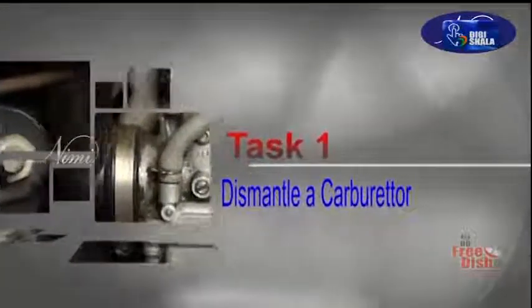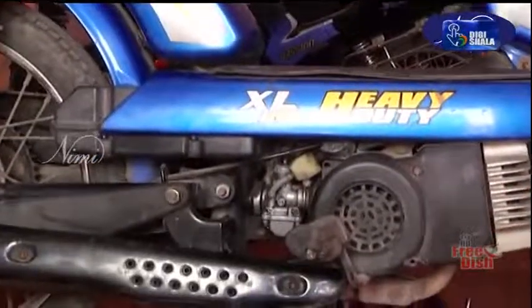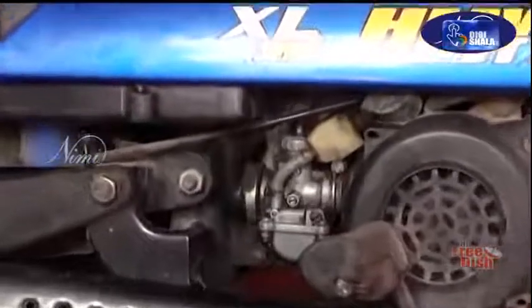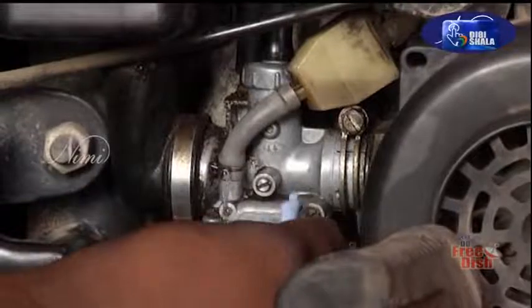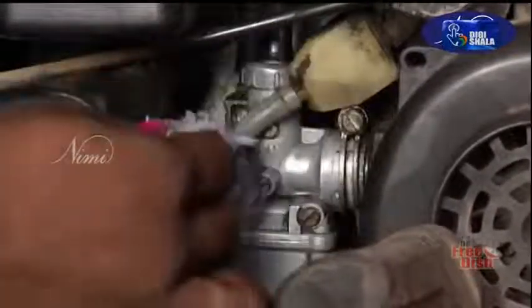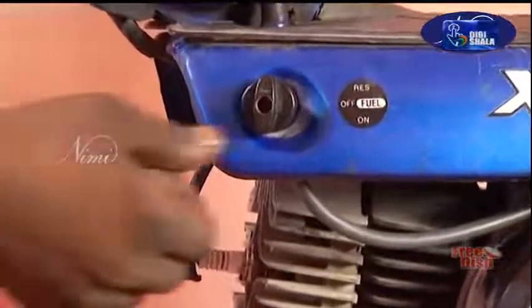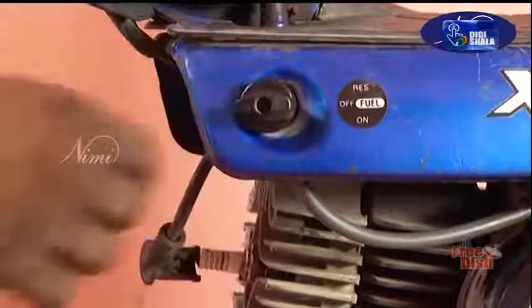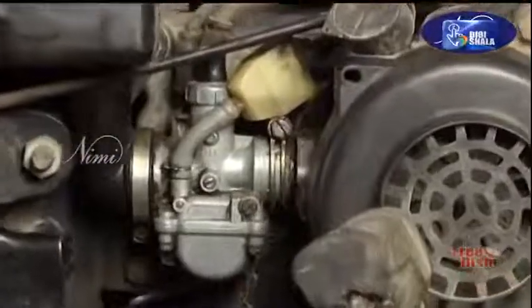Task 1. Dismantle a carburetor. Locate the carburetor. It will be below the fuel tank. Wipe any dust, oil on the carburetor with a clean cloth. Close the fuel tap to prevent wastage of fuel due to overflow when the fuel filter hose is removed.